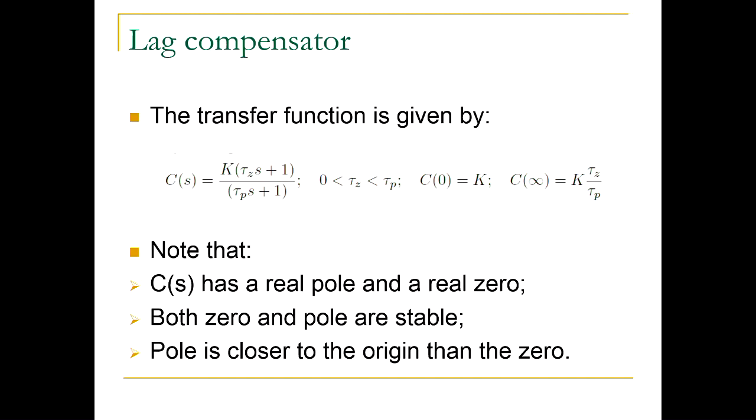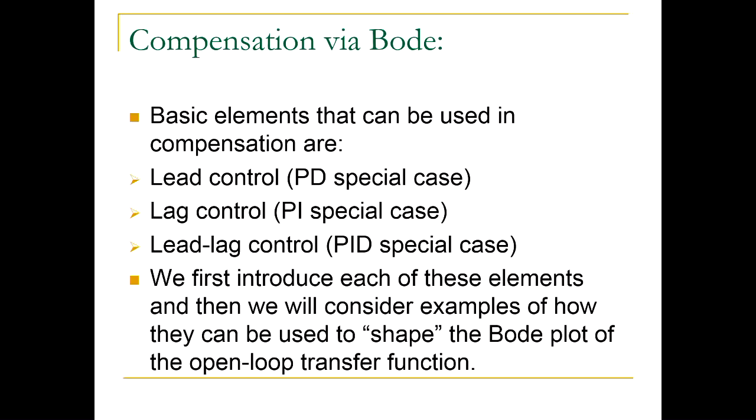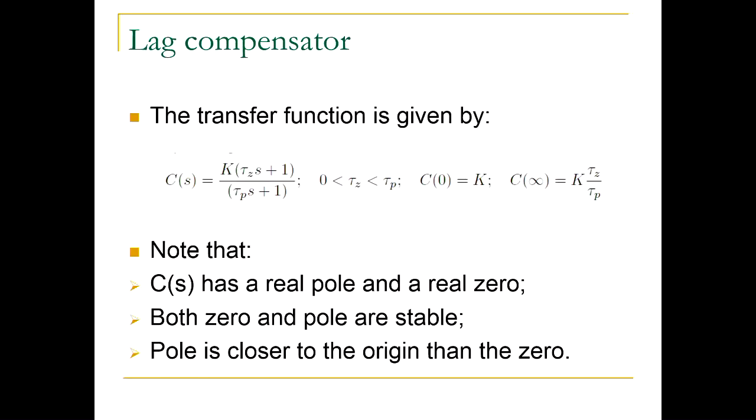One of the compensators that we will consider is lead lag, and then PID control is a special case. So you can do PID controller tuning using Bode diagrams, using the techniques that we will present here. All right. So that's a very systematic approach to tuning PID control. So here is the first compensator. It's called a lag compensator. By the way, lead and lag compensators would look very identical, except that the devil is in the detail.